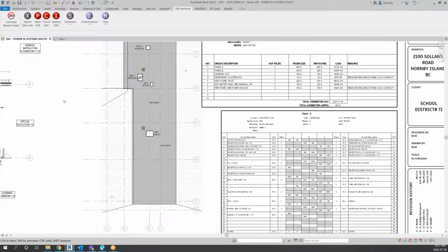Yeah. And if you can set up common libraries, we've been talking with the one firm we work with that uses Revit about us developing a set of families for them, which will contain all the electrical information we need. And then we would expect to link in their model and use Copy Monitor to then make those devices live in our project. Because I don't believe we would be able to schedule properly on elements in a linked model. We would have to Copy Monitor them in. Or the other thing we could explore is just sharing the same model with them, but I think that's going a little too far outside what I'd be comfortable with right now.